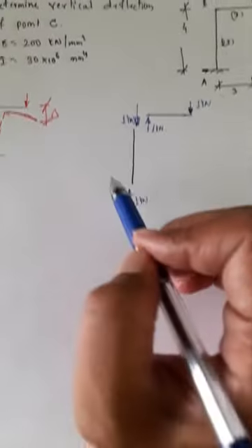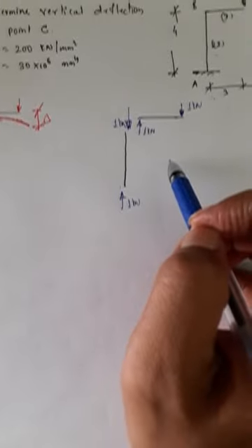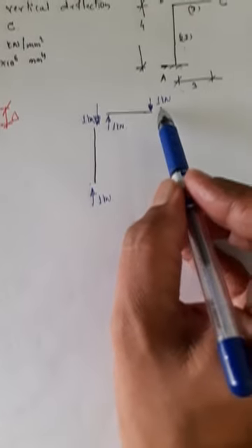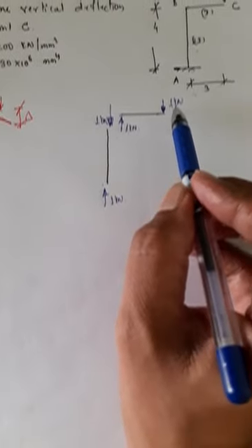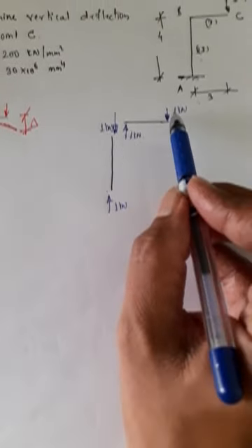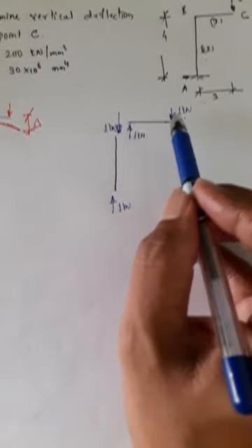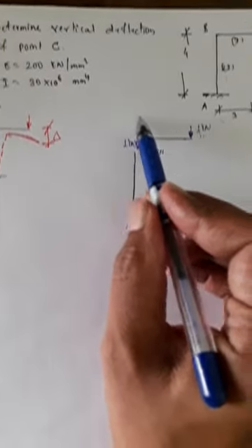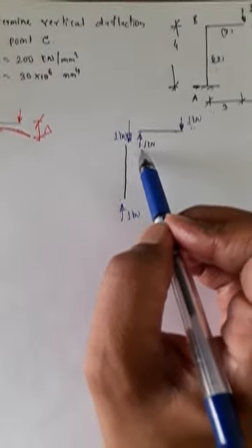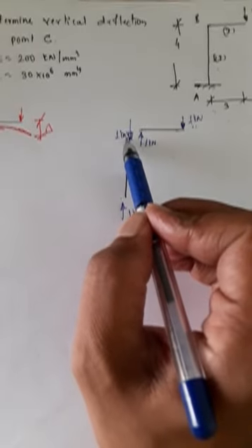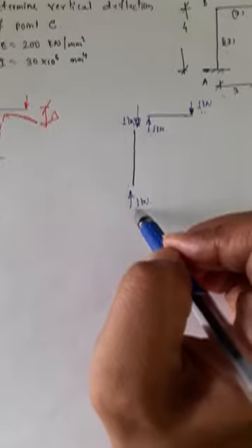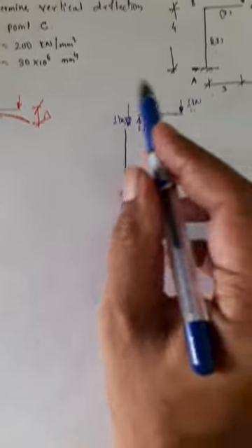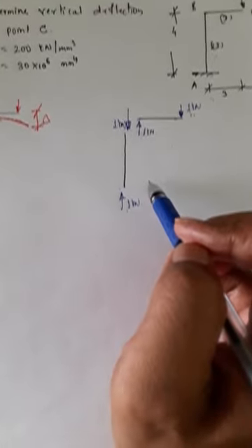So this makes the whole structure in equilibrium for point loads. First consider this section, BC section, 1 kilonewton here. At this end, equal and opposite to this, summation V is equal to 0. Now consider this joint, this is acting. For this, apply equal and opposite this. Now, to balance this, apply this equal and opposite. Hence, this whole thing is in equilibrium now.